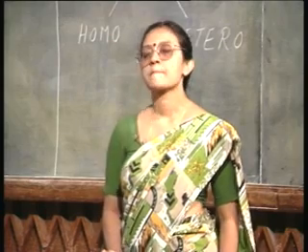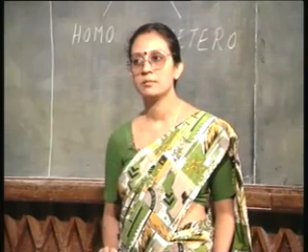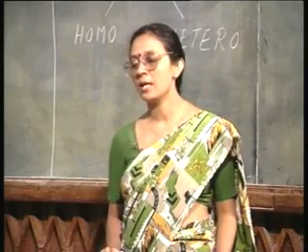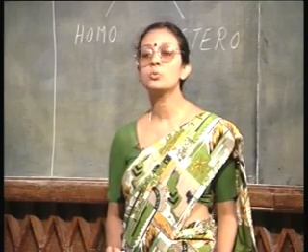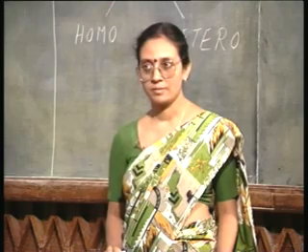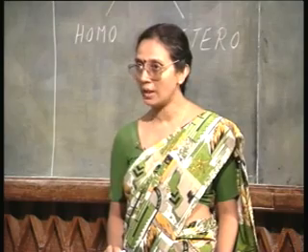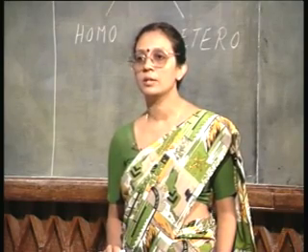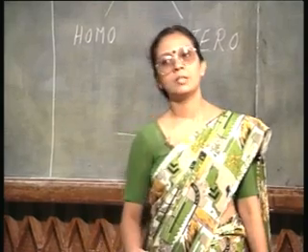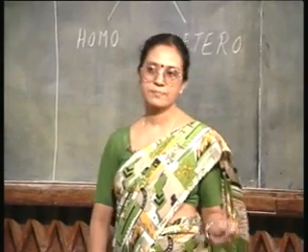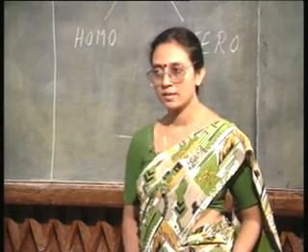In contrast, if I have a certain crystal as the substrate, as the bulk material, and I want to grow something else on top of that, that is, if the material of the epitaxial layer is dissimilar from the bulk material, then it falls under hetero epitaxy. A very common example of hetero epitaxy is silicon on sapphire. You might have heard of it, SOS, silicon on sapphire.